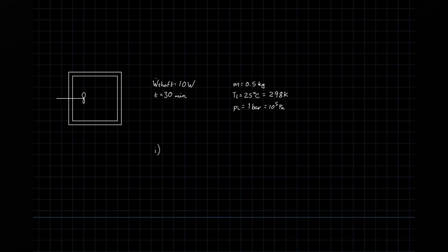So I suppose step one for this problem would be to find our internal energy again. Now, there are a couple of things that are nice about this. First of all, it's insulated, so we know that our heat flow will be zero because there can be no heat flow between the inside of our tank and the outside. That means that Q dot equals zero. And we also know that the volume cannot change because it's a rigid tank, which means that only the pressure increases, not the volume. This makes some stuff easier.